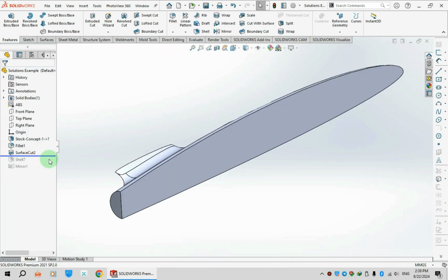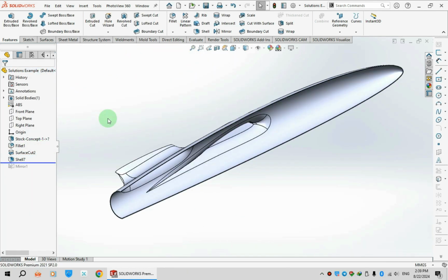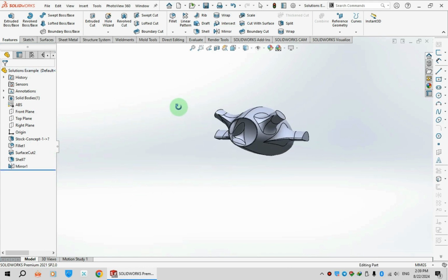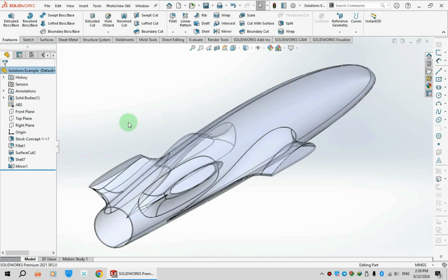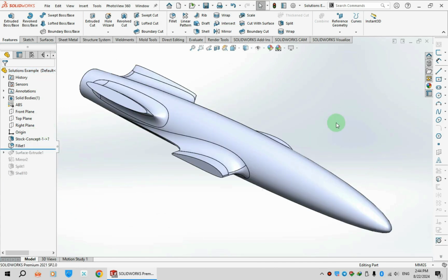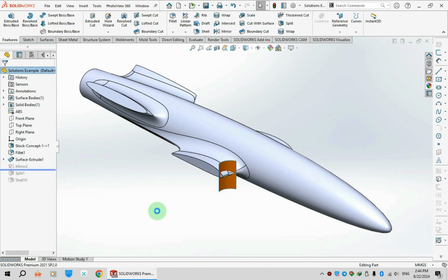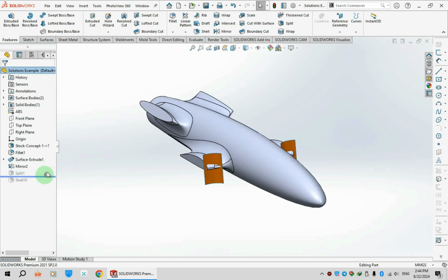Another solution is to divide the part into separated sections. Create separated shells and combine them again. In some cases, you can exclude the area that caused the error by dividing it, doing the shell and combining it back to the model.